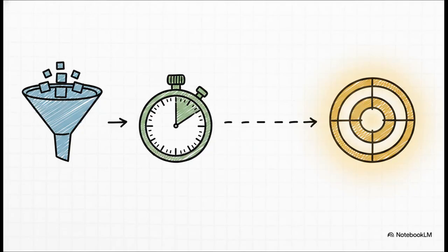All right, so with those basics down, we need to define the physical limits of the line itself. First is the bottleneck rate, or RB. This is the rate of the workstation with the highest utilization. It's the absolute ceiling, the capacity limit of your entire line. Next is raw process time, or T0. This is the sum of the mean effective process times of all stations. Imagine dropping one single job into a totally empty factory where it never has to wait. That time is your T0.